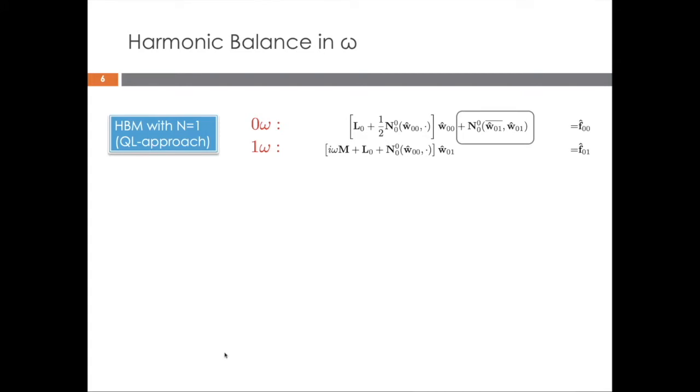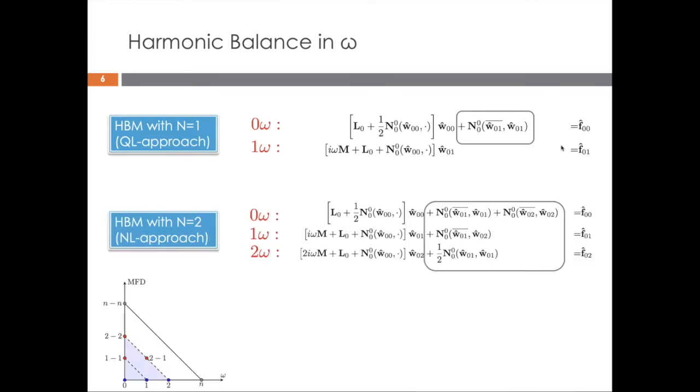Here, the top equation is the mean flow equation forced by the nonlinear stresses resulting from the self-interaction of the first harmonic. And of course, if you keep increasing the bifurcation parameter or any kind of control parameter, which in our case is going to be the amplitude of the forcing, you need more and more harmonics to converge to the true solution you would get from a DNS.